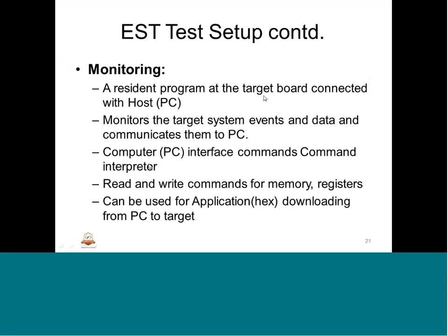There is a protocol or handshake involved between the target board and the host. Generally, the commands are read and write. Mostly they are used for memory and register operations. And there are also systems which use the same interface for downloading the target application. That is, the image, the binary, can be downloaded onto the target with the help of a PC.